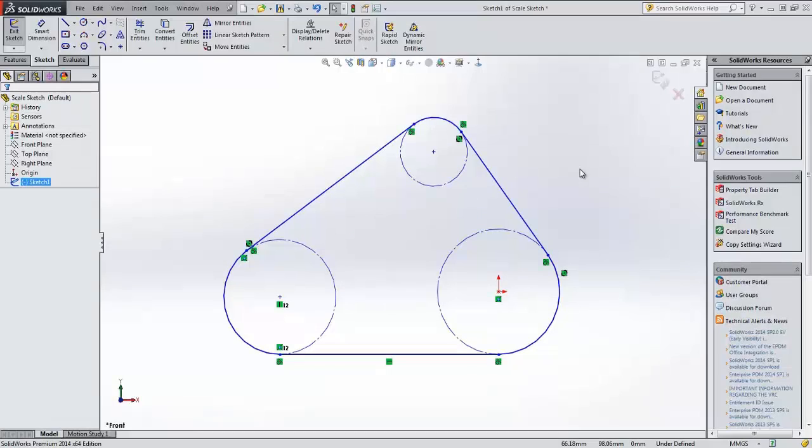When it comes to sketches in SolidWorks, we've always advocated for the free sketch method, where you throw in your sketches first, and then you go ahead and make it robust by adding in constraints and dimensions. However, it is sometimes hard to gauge the actual dimensions due to the scale of the sketch. I'm sure many of you have seen where when you put in the first dimension, the sketch either scales up